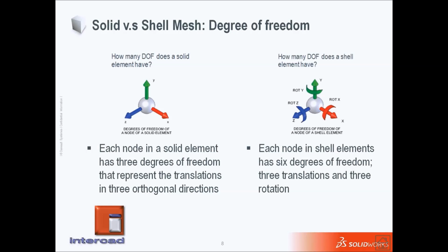And this is one very important note you have to always remember if you are using a mix of solid and shell elements, where in their intersection line, as the shell elements are capable of rotating, we might build up a rigid body condition or a hinge condition, and we may produce unrealistic displacement. Therefore, in this option, we should be very careful to bond the mesh and the nodes and make sure they are correctly connected to each other.